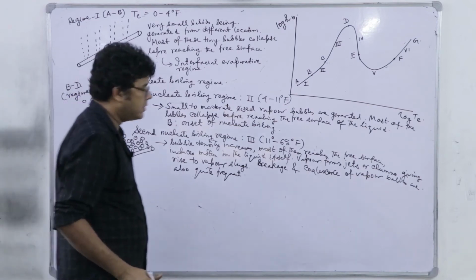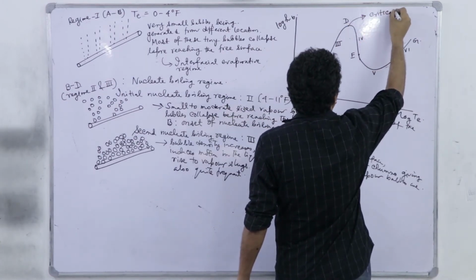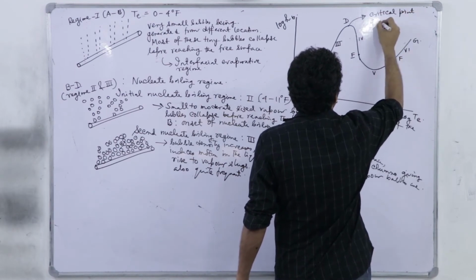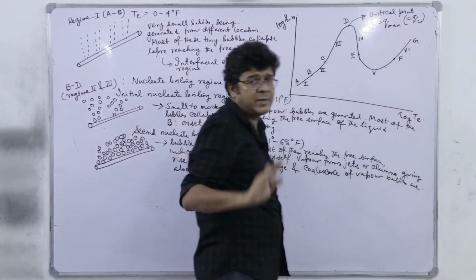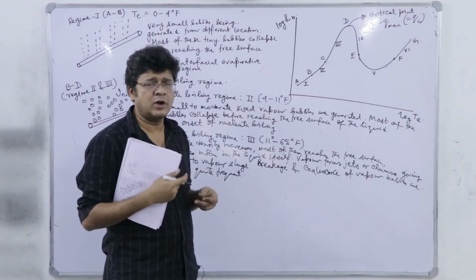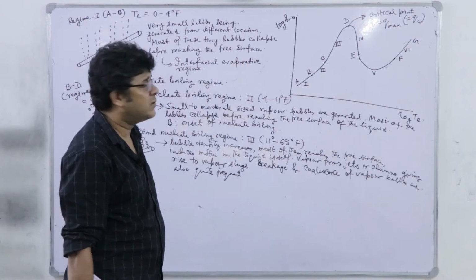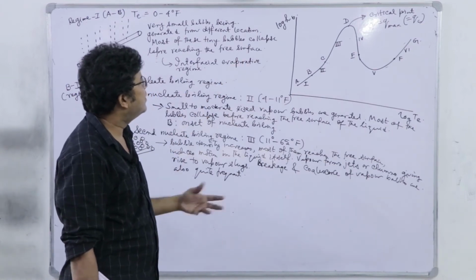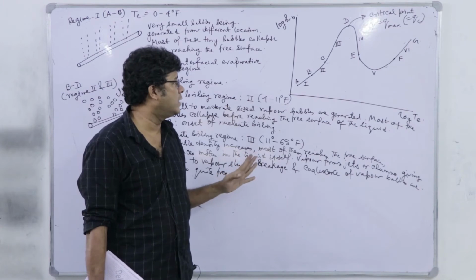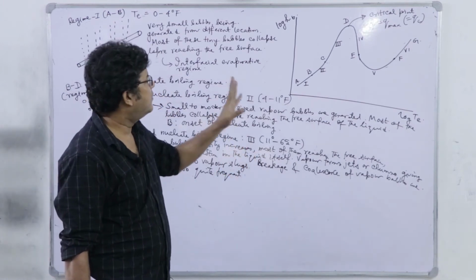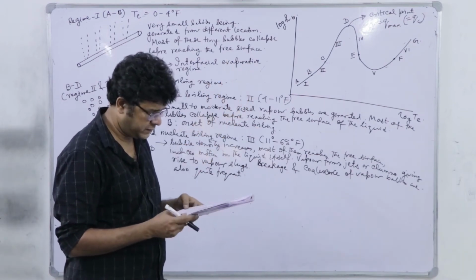And this point where the flux reaches the maximum, it is called the critical point where Q is equal to Q max, and that is QC, the critical point flux, which is the maximum flux, and there are certain empirical equations, we are not going to discuss it. This critical flux can be expressed in terms of T and other liquid properties. There are a lot of equations, right, based on these empirical studies, but the form itself is quite complicated. So, that is why we are not going into the detail, and it is not recommended that we have to mug it up, right, we do not require the expressions.